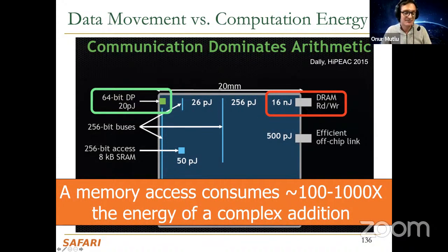That's 800x, right? So the question is, does it really make sense to bring the elements to a processor, CPU, or an accelerator so that you can do this very simple computation today, right? And the idea in processing in memory is really clearly to do the addition or floating point multiply and accumulation on the DRAM side so that you don't exercise this heavy interconnect and so that you don't pay the penalty cost of 800x energy increase.